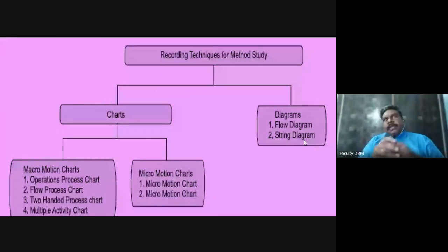And we have another method to measure the distance also. We take the map, pin it with pins and make the threads, and we see how much distance the agent has to travel. That is the string diagram, because to minimize and understand those works, we use that.